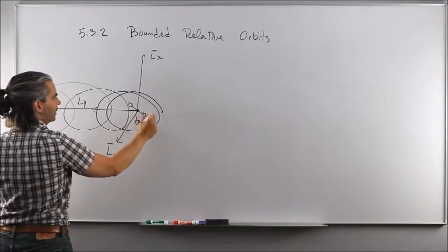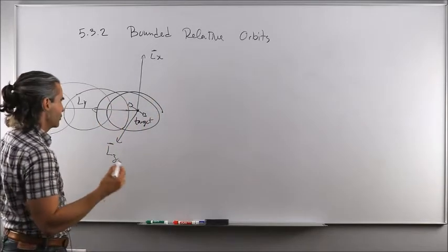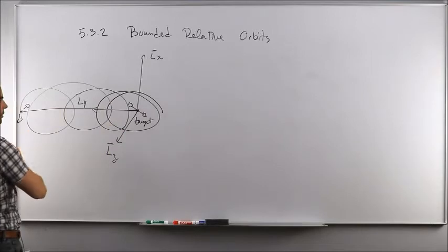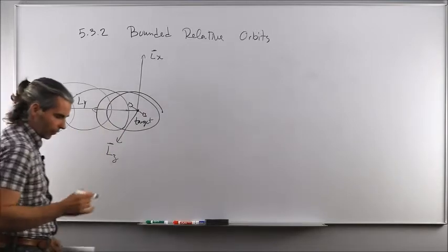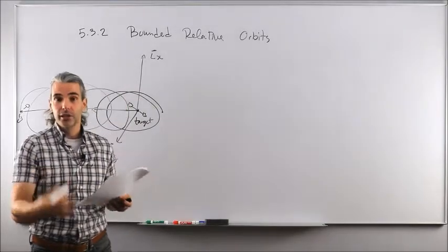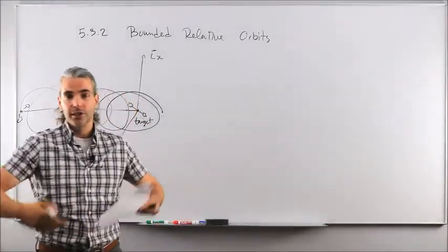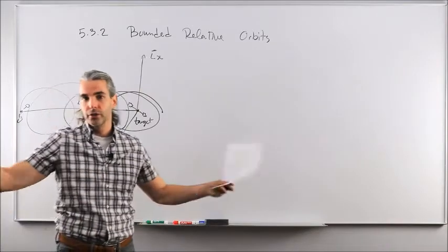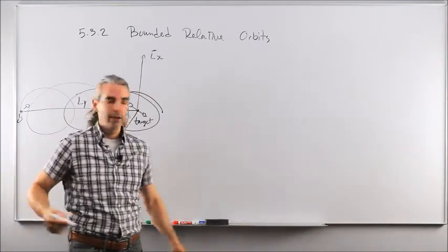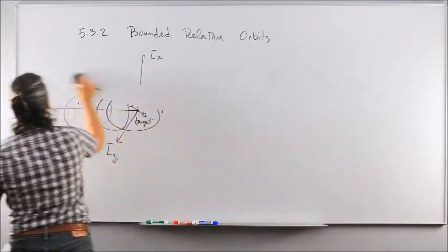That is because the linear drift term, which was inherently part of the y solution of the differential equations of motion, didn't get cancelled. So that's not good, because formation flying implies that both spacecraft will continue to operate in close proximity as time goes by. Otherwise, it's no longer a formation, it's just two individual spacecraft orbiting the Earth. So what we want to get is a bounded relative orbit instead,